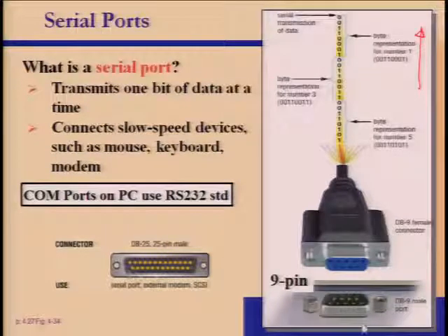And over here you can see that there's a 9-pin port, right? And this is the male type. So in order to connect to the external device, you need to find another connector, also 9-pin, however it's of the female type, so that you'll be able to connect to the external device. I mentioned just now that there are also 25-pin connectors, right? So in that case, you need to find a 25-pin port.